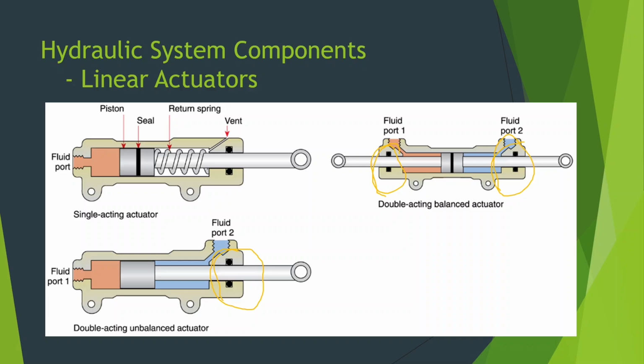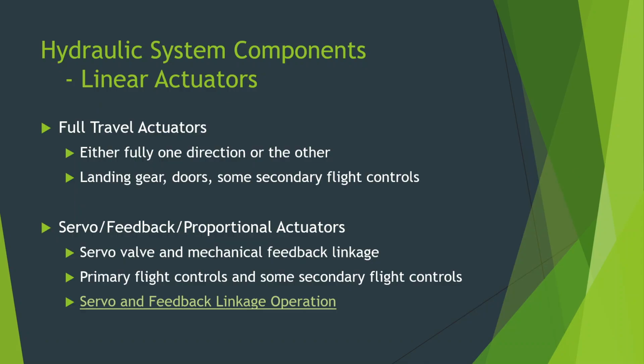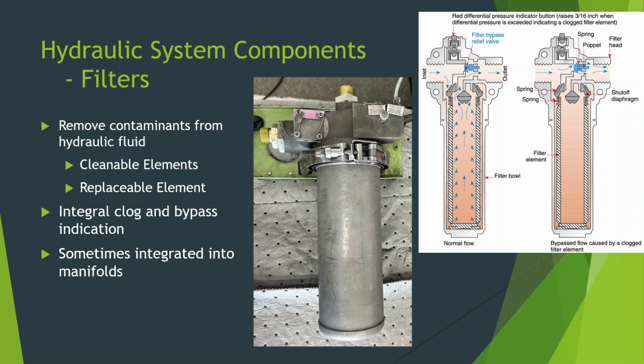Okay. The other part of that is that fluid that coats the actuator, hydraulic fluid, over time in particular, gets sticky. And so things like dirt and dust stick to that. And when that actuator retracts, it's going to pull a small amount of that dirt and dust back into the actuator, into the right side, for instance. And that will end up going back through the return side and it gets into the system. So we need to be able to remove that over time. And that's why we need a filter. Even though they're closed systems, we have to have filters in there, mainly to remove that.